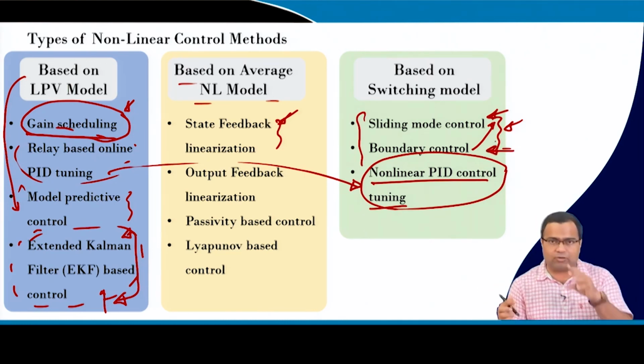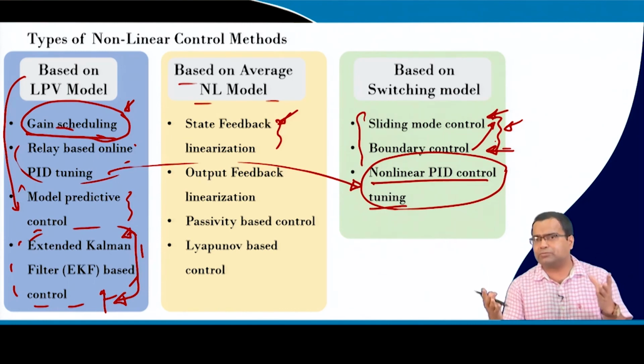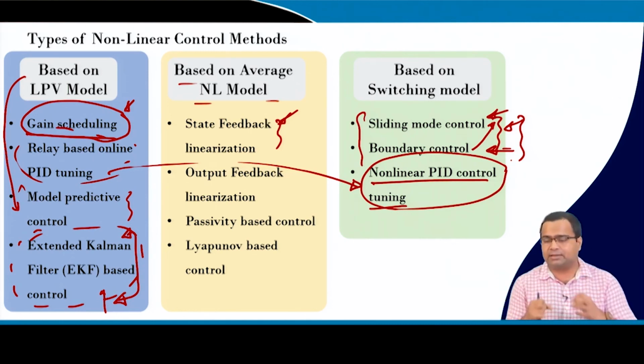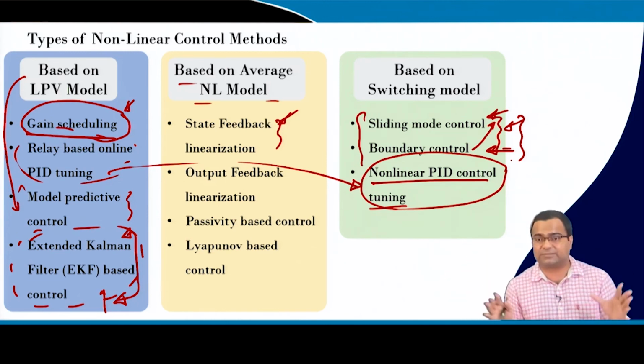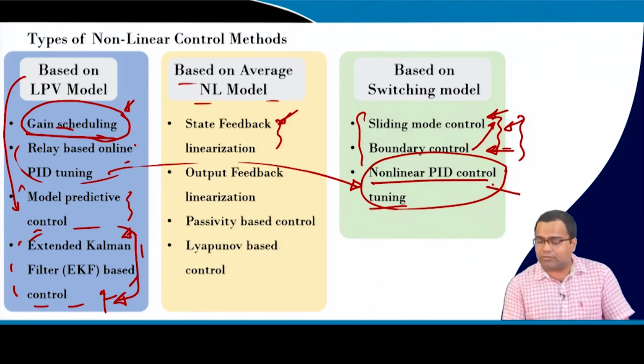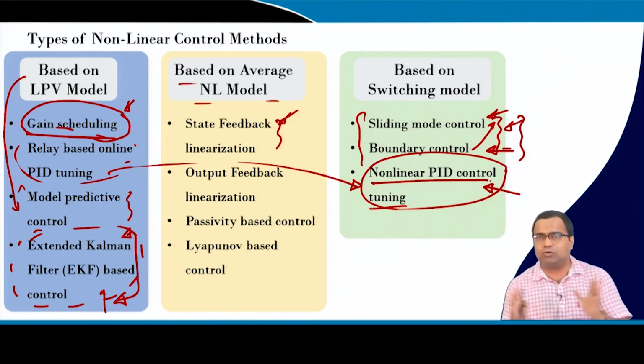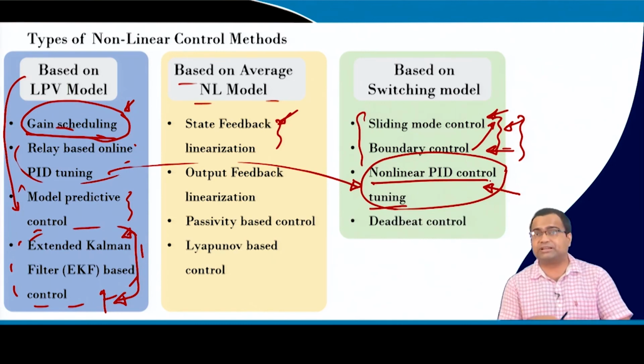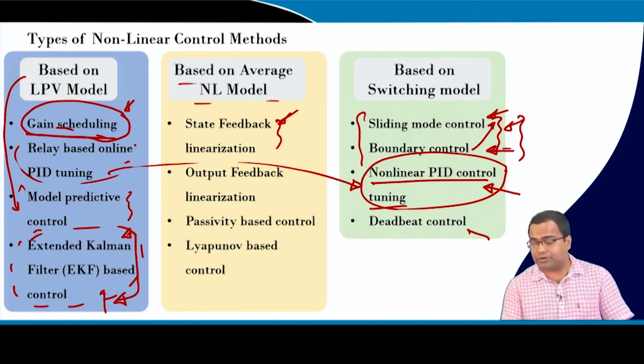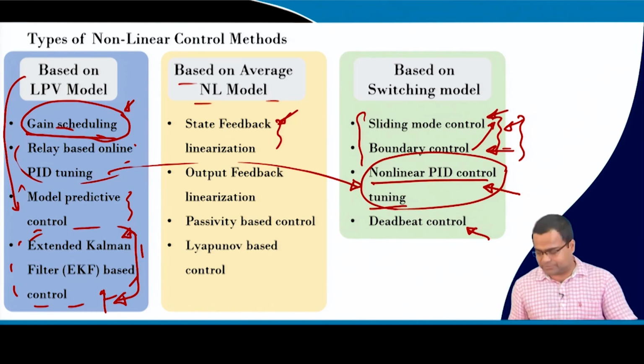So, it can require more resources, and most of the time we interface this kind of control with a PWM control under steady state. So, they combine nonlinear and linear control to achieve the desired response. But here what we are going to talk about is that a single PWM control can achieve the whole performance. You do not need a separate controller, and you can also use deadbeat control, like time optimal control, to achieve the fastest response.